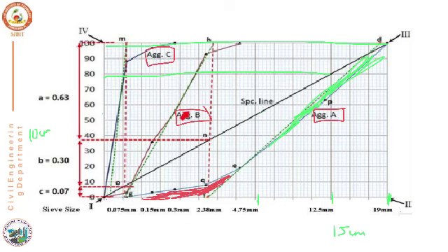So this dotted line in the green represents the balancing line. After drawing the balancing line, join 100% of one balancing line with the 0% of the other balancing line. So this is how you need to draw that. This dotted line indicates the 100% passing of one balancing line to the 0% of the other line. You can see that these lines have met the desired gradation line at some point. Draw a horizontal line which is parallel to the x-axis to meet the percentage passing line.